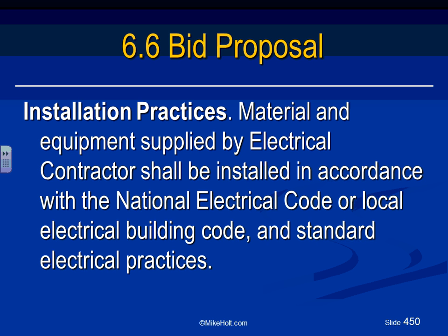Material and equipment supplied by electrical contractors shall be installed in accordance with the National Electrical Code or Local Electrical Building Code and the standard electrical practices. The standard electrical practices will cover a few things. Somebody will force you to use rigid above that one. I mean, that's expensive to put rigid. Well, that's why I want my branch circuit rigid. Unless it's specified as rigid, the standard electrical practice does not say rigid above a suspended ceiling.